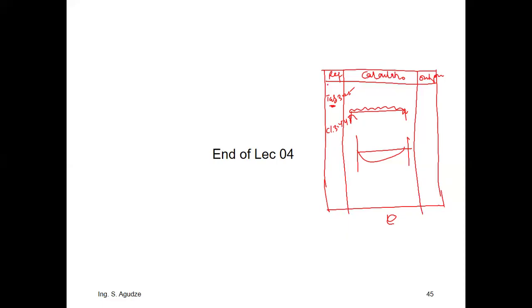And we have learned this. We have gone through a few of the formulas, and all these formulas for the doubly reinforced section, you can find them in clause 3.4.4.4 of BS 8110 part 1. And this is the same code you'll be using for the exam. I don't see why you would want to have everything in your head, because expert structural engineers, everybody, is using the code.